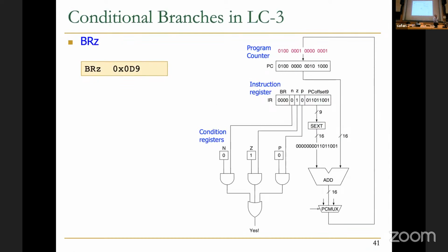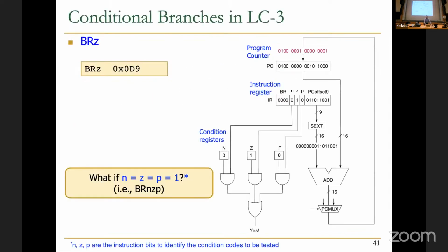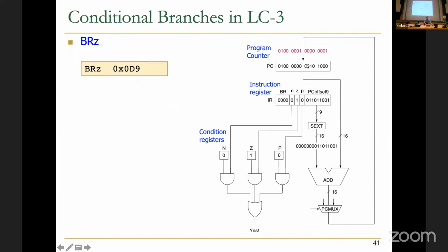They are special purpose registers, 3 1-bit registers each. These are exposed to the programmer. It has to be specified in the instruction set architecture because there's an instruction, as you can see, that's manipulating them, right? Actually, all instructions are writing to them in LC3 because all instructions can set condition codes. Well, maybe all is too much. Some instructions do not set condition codes. Every instruction that's writing to a destination register is actually setting the condition codes. I should be more specific. Okay, basically, let's take a look at how this is executed.